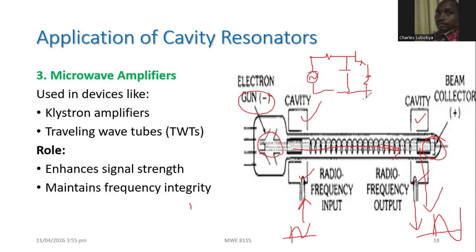Again, this is okay. Then you have a resistor there. Then you have positive VCC there, positive voltage. Okay, so this signal here is V. It's AC normally that you want to amplify.